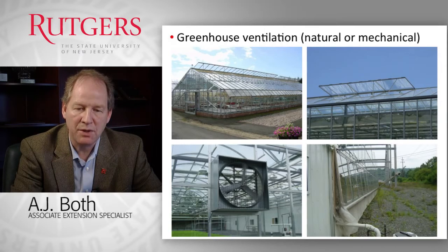Another ventilation system are the Dutch Venlo greenhouses that typically only have vent windows in the roof, and depending on the location of the window, the prevailing wind direction and the wind strength, those vent windows can act as inlet openings or outlet openings, or perhaps even as both an inlet and an outlet opening, depending on the pressures and the airflow created at that location.